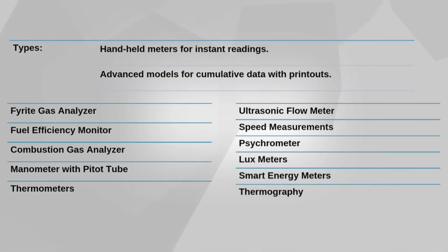Lux meters are essential for measuring light intensity in the visible spectrum. They use a light sensitive cell to evaluate incident light against the human daylight sensitivity curve, providing a measurement in lux. While effective, they require current and different correction factors for each light spectrum. Advanced lux meters are optimized with optical fibers and lenses to match the eye's light sensitivity curve, simplifying the correction process.